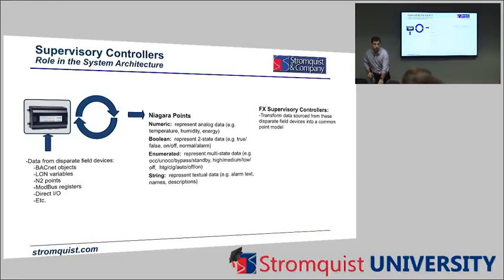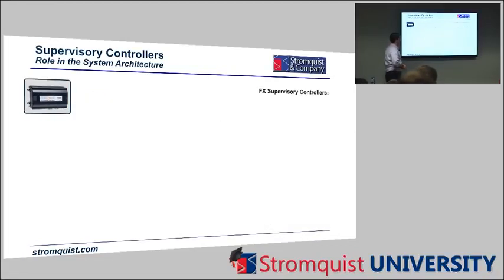So if I have 100 different buildings, and say 100 different Jaces, no matter what brand it is, and one person in control, is it all going to communicate together? It can. And that goes with licensing too, Carl. Yes, you can get Jaces, any Niagara Jace, I should say, because there's an older R2 system that's going away. But Niagara Jaces can talk to each other over a common Niagara network, and it doesn't matter the brand.